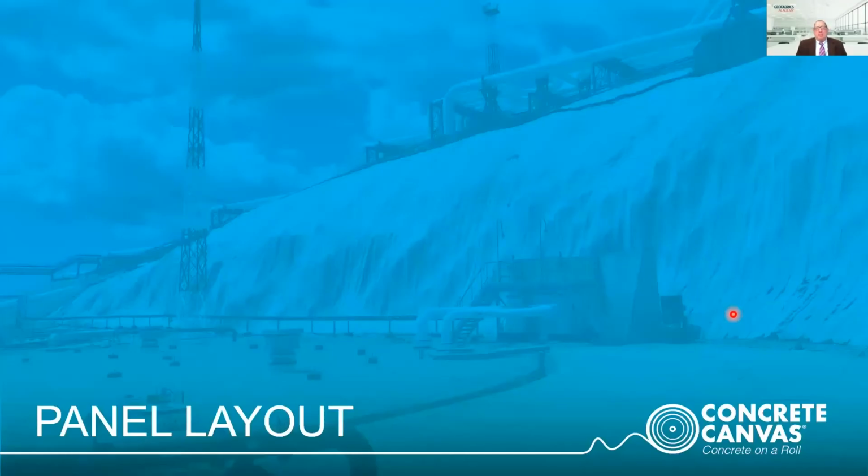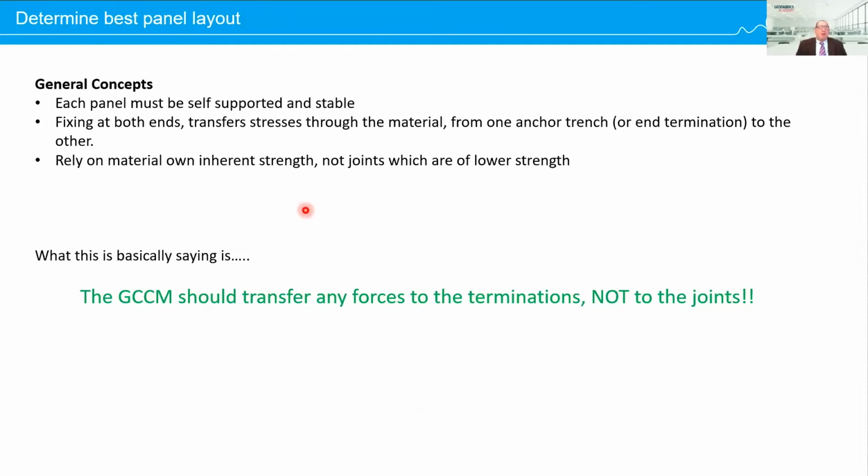The next step in the process is considering the panel layout. General concepts for layout of panels is each panel must be self-supported and stable. Fixing at both ends transfers stresses through the material from one anchor trench or termination to the other. So we rely on the strength of the material, not on the joints, which are lower strength, to transfer stresses. What this is basically saying is a GCCM should transfer any forces to the terminations and not through the joints.